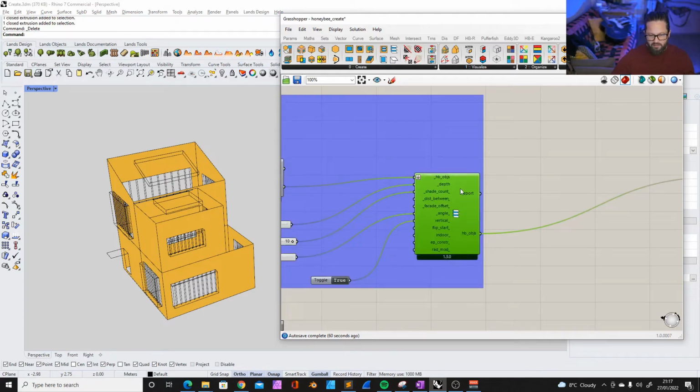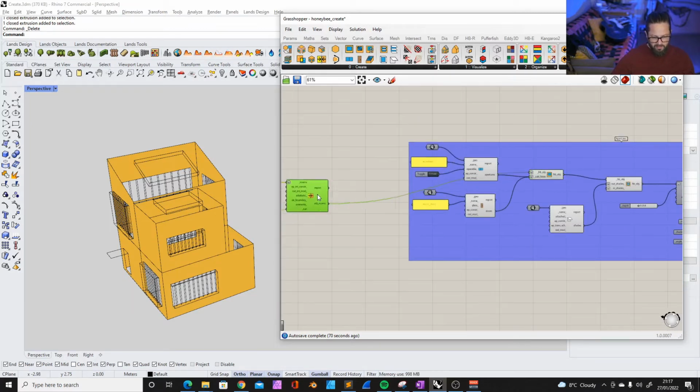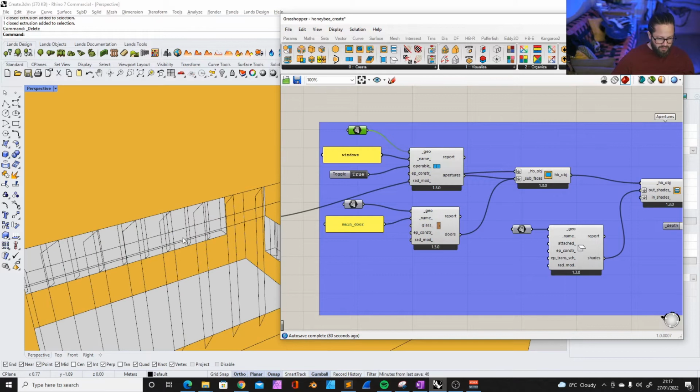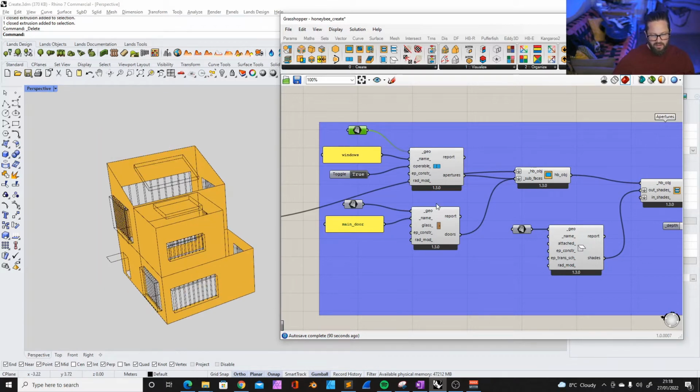So after that, we applied everything, and you always need to apply one by one. So we apply first the subsurfaces, which is the door and the apertures. That can be done in one step. So we basically feed the current rooms into this object here, add subsurfaces, and we add these two things here. So we have surfaces for that. The window surfaces need to be aligned. They need to touch the walls and also the door.